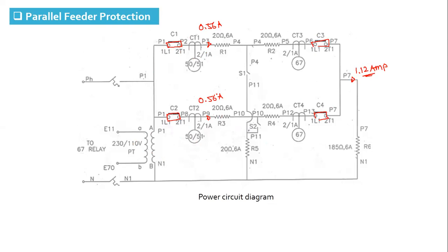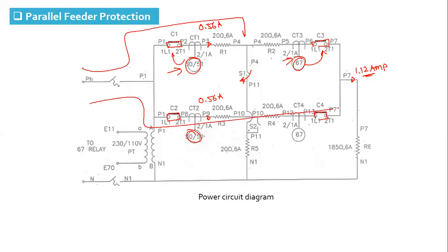Then in this experiment, we are going to close switch S1. So fault will be on feeder 1. So these 2 relays will pick up, and initially these 2 relays will trip and open the breaker at both the ends, because fault current is fed from both the ends. So it is required to trip the breaker at both the ends. In case this directional relay fails, the backup will be provided by R3 and it will trip the breaker over here, because this relay is never going to operate for a fault on line 1. It is in the inoperative direction.